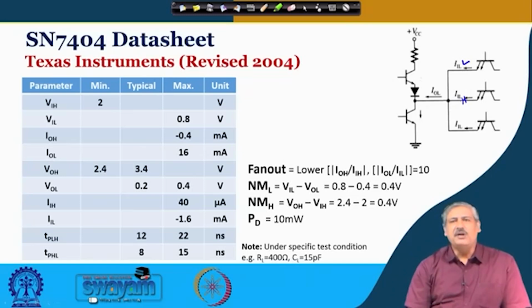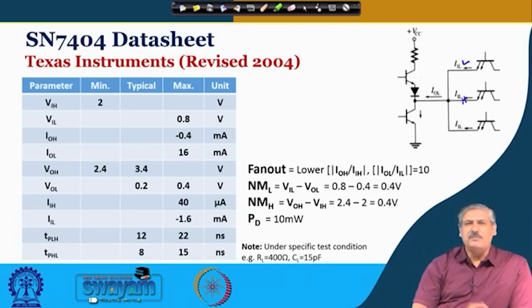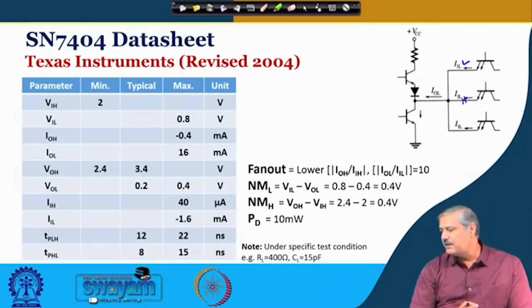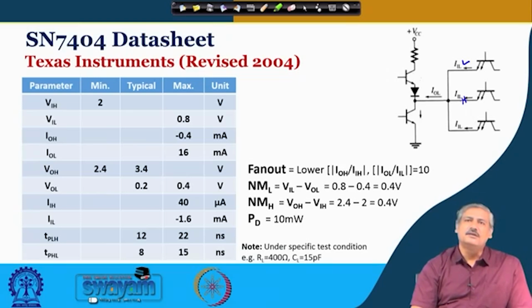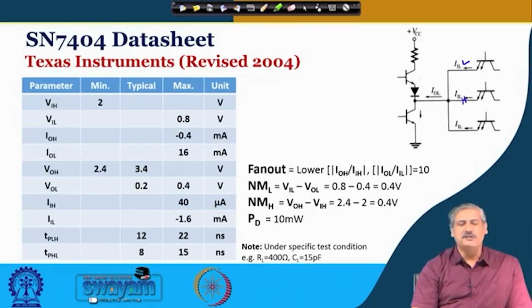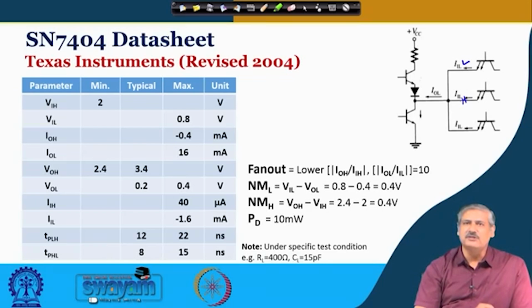Now, we look at the one practical. So, I said that was an estimated value. So, if you look at any standard manufacturer's data sheet, we shall see how the TTL gate inverter 7404, okay, what are the different parameters, how that has been specified. Okay. So, we are already familiar with terms like VIH, VIL and so on. VIH is the minimum voltage at the input side which is considered as high. Okay. Any voltage above that is considered as high, there is no issue with that.